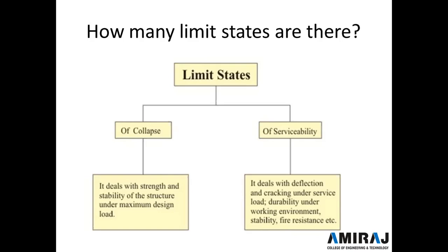Now discussing the limit state of serviceability, it includes deformations and deflections, vibrations, repairable damage or cracks due to fatigue, corrosion and durability, and fire. This limit state of serviceability is related to the satisfactory performance of the structure at working load, right?